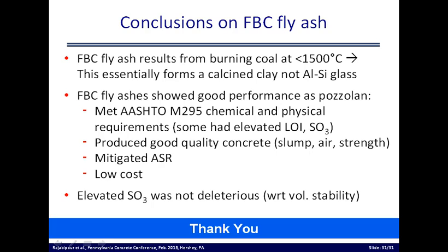What was the cementitious content of the control mixes? Let me actually guide you to the proper slide. So if we go to, for example, slide number 10, you see that the cement content is 588 pounds, which is on the lower range of what's specified by PennDOT. The other mixes that